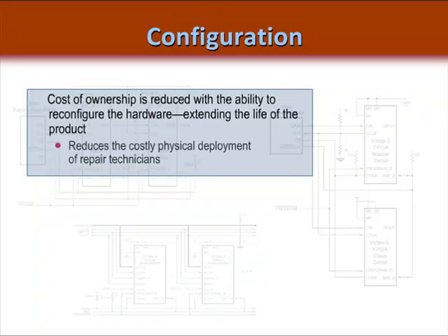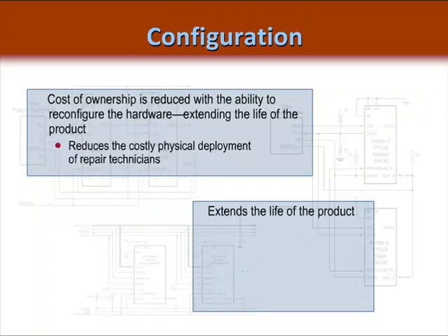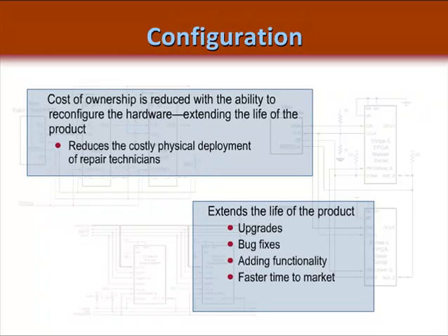As was mentioned earlier, reconfiguration of the FPGA allows the device to be modified, fixed, or the design upgraded without wasting the device. This extends the life of the product a great deal. But most importantly, it enables a faster development time for our customers. Instead of lengthy development times, they can simply make the design change and program the same device. There have also been plenty of applications where a single FPGA was reprogrammed in system with a different bit stream to enable the FPGA to serve multiple purposes at different times.